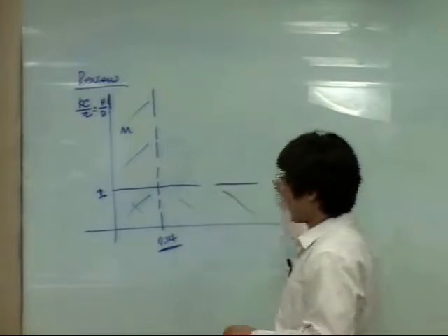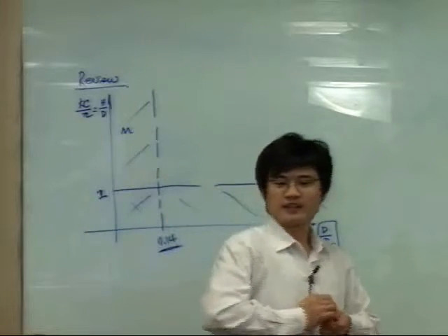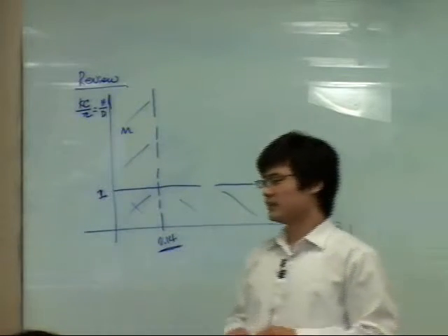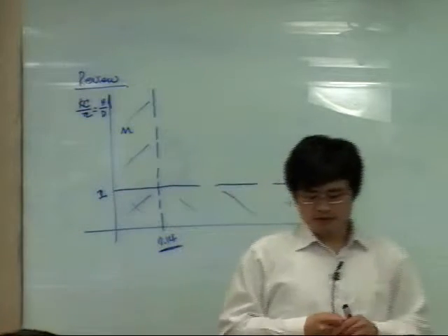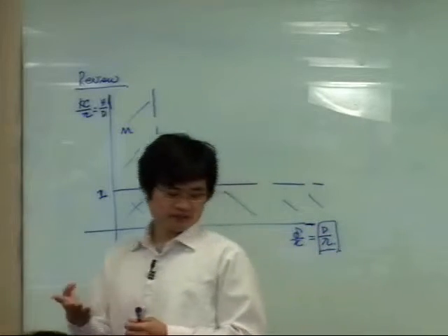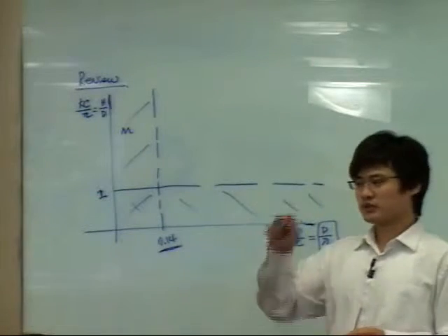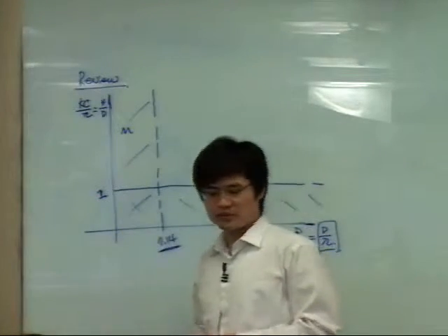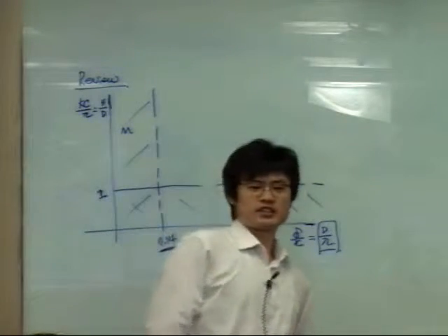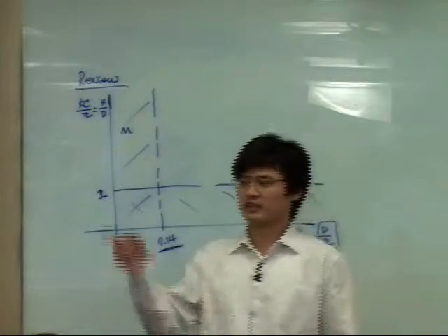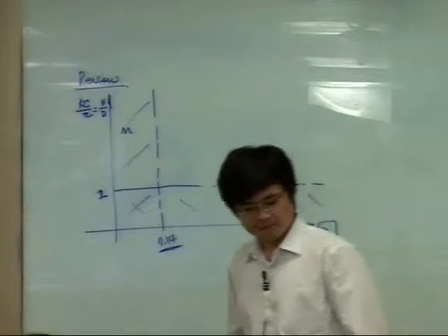And after I introduced you this chart, we went through the Morrison equation and how to determine the inertia coefficient, the drag coefficient, and I talked about the Froude-Krylov method. In this region you assume the diffraction from the structures is small, and you find the pressure around the structure surface, and then do integration to find the total force.